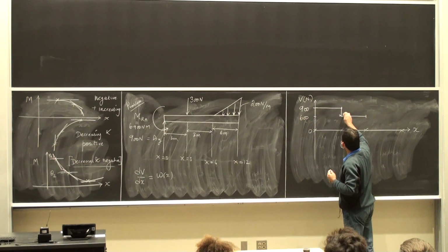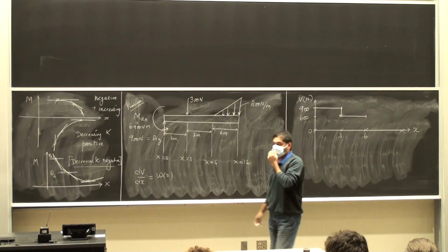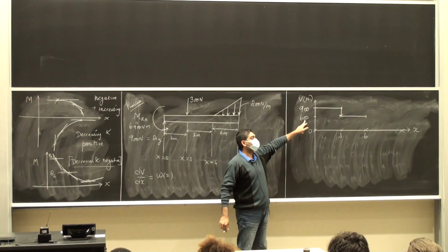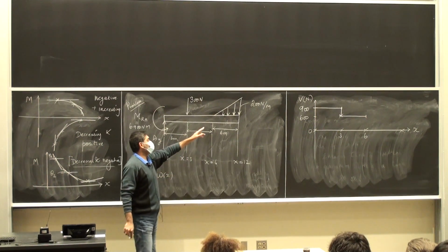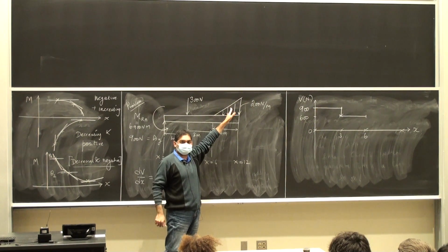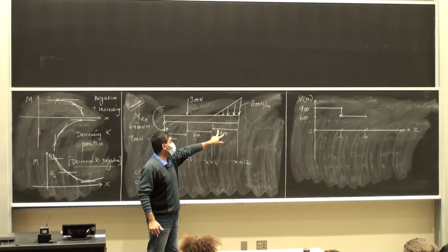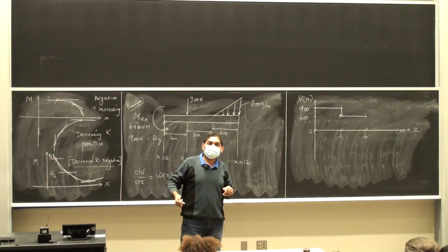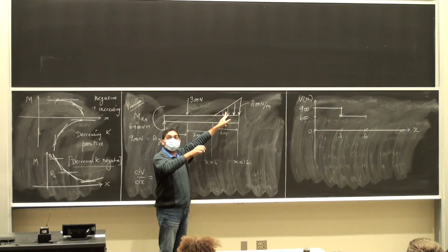Then comes the clincher. So this is 3, this is 6. I am currently at 600 newtons. I have to check and see if I calculate the area of this triangular distributed load, is it giving me 600 newtons? What's the area of this triangular distributed load? Half times the base times the height, which is obviously going to give me 600 newtons, with a negative sign because the intensity of the load distribution is pointing down.